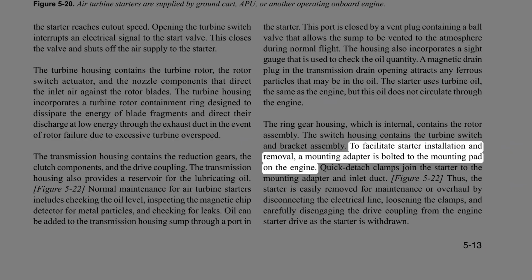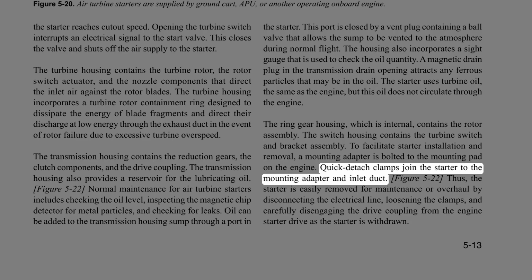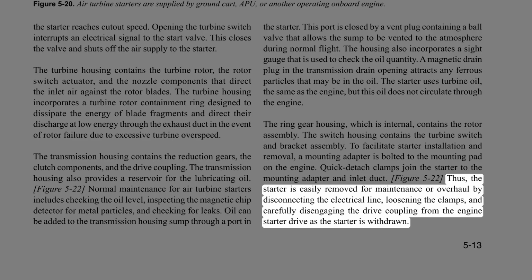To facilitate starter installation and removal, a mounting adapter is bolted to the mounting pad on the engine. Quick detach clamps join the starter to the mounting adapter and inlet duct. Thus, the starter is easily removed for maintenance or overhaul by disconnecting the electrical line, loosening the clamps, and carefully disengaging the drive coupling from the engine starter drive as the starter is withdrawn.